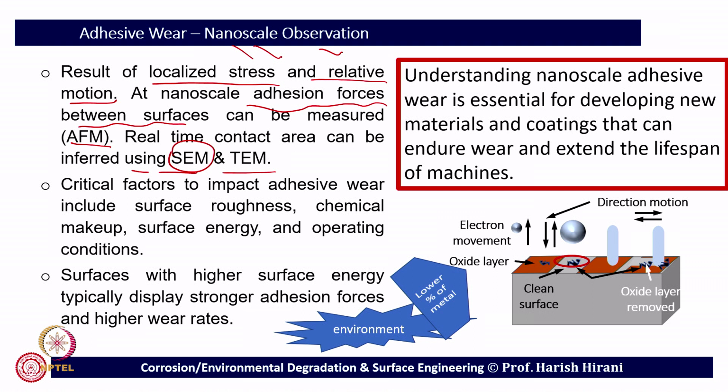So, these are the important aspects. Now, if I think from a wear point of view, there are some critical factors for adhesive wear, which is surface roughness. We need to minimize the surface roughness, but we also mentioned that we need to texture, we need to design a roughness if we want better and better results.